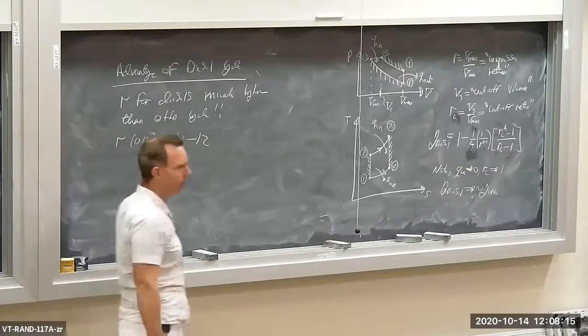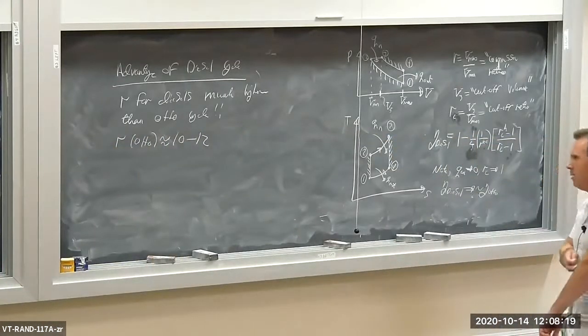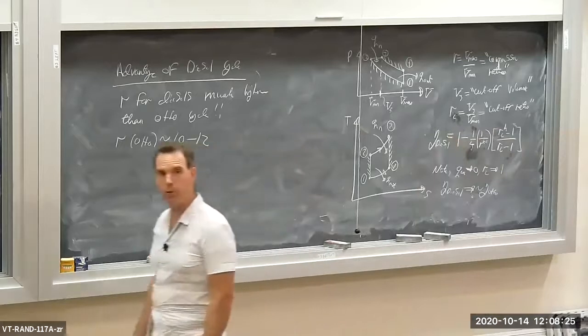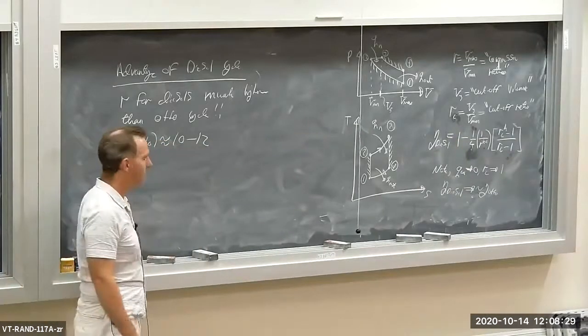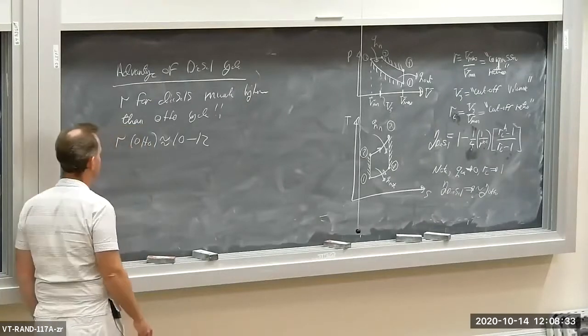Anything higher than around 12, direct injection is helping with that a little bit, but anything higher than 10 to 12 and you start getting knocking, okay? You can use higher octane fuel. Higher octane fuel is more resistant to knocking, but the highest compression ratios for the Otto cycle are around 10 to 12.